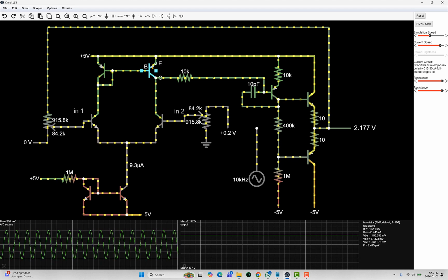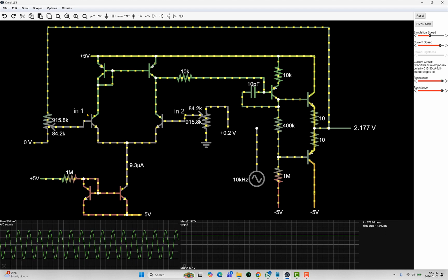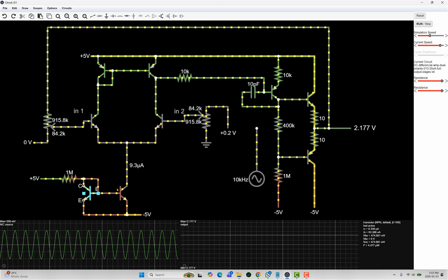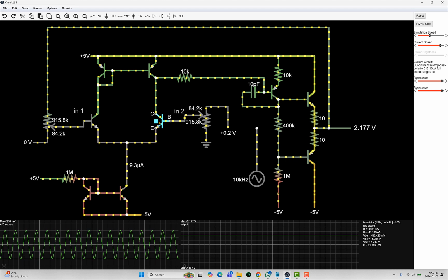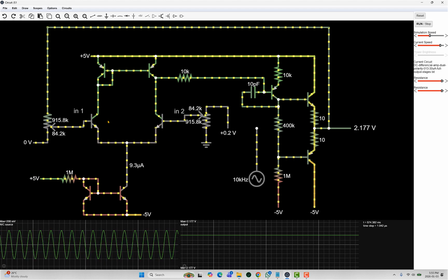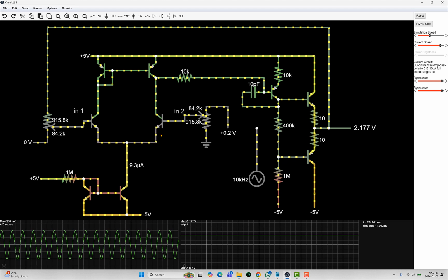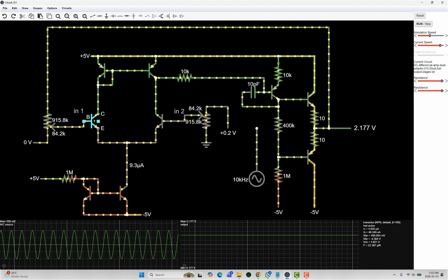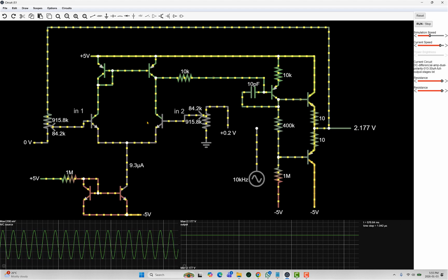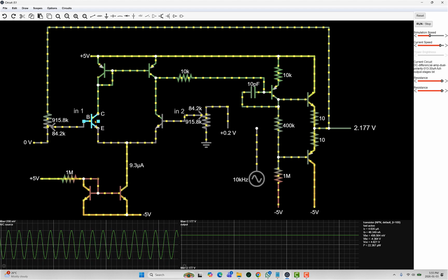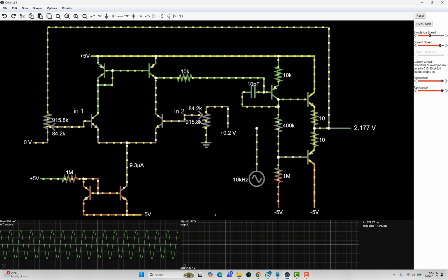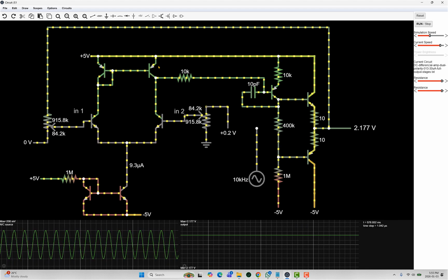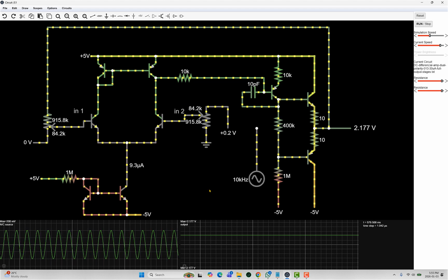I don't know how accurately matched these two differential transistors have to be. And these ones here, I don't think are too critical, but I'm wondering about these. Again, I haven't built it. So if you're building it, you can just try garden variety ones, and then maybe if it doesn't work well, you can try to match these transistors using your meter, matching the current gains of these transistors, maybe these two as well. These ones aren't as critical, but these four are probably the ones you might want to play with. Other than that, I think it's pretty straightforward.